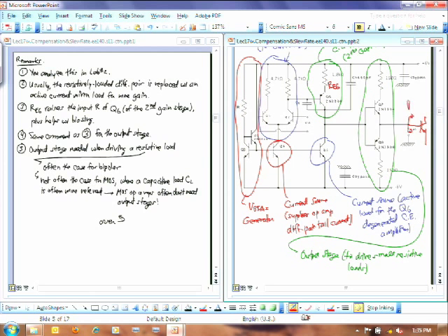Okay? If I took this as just my output, what's that resistance? I was just looking for large. But you can write it out, right? The RO times 1 plus GM times this R, etc. But that's a very large resistance. And so that means that this stage in itself does not make for a good driver stage, right? Because if I take a large resistance and then I try to drive a small resistance in shunt with that, that voltage divider is going to kill our gain, right?